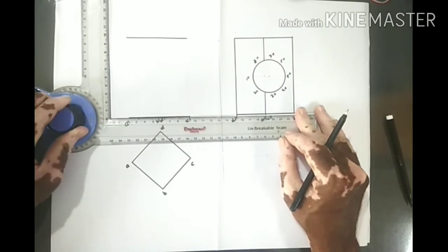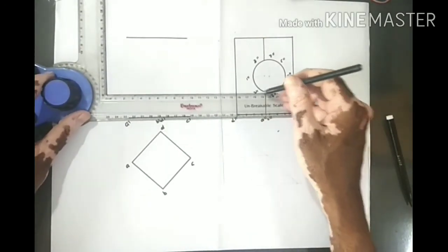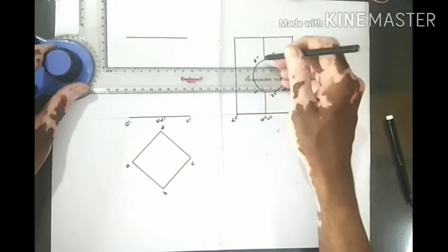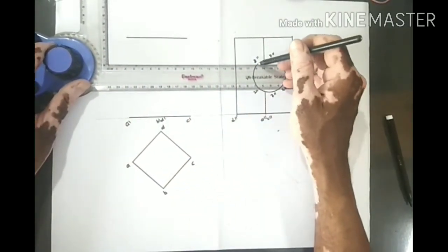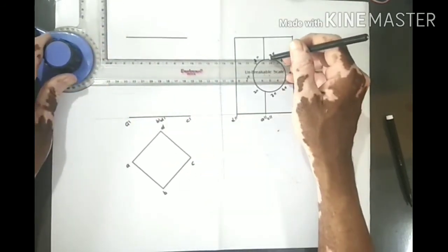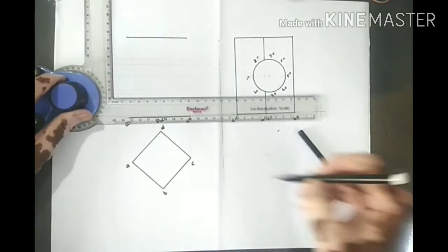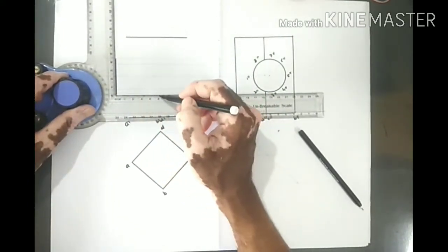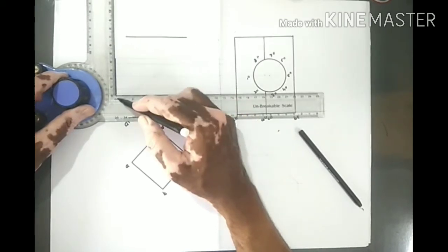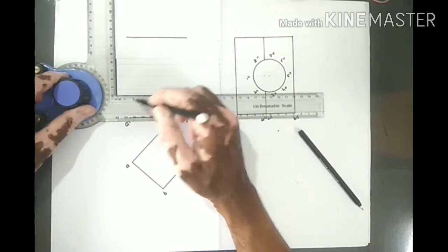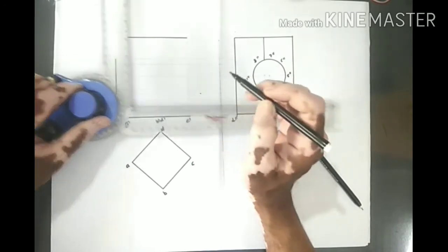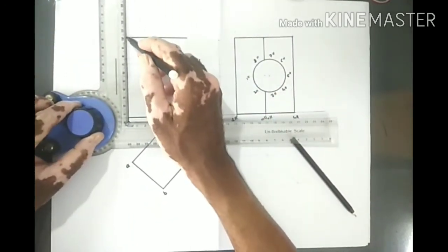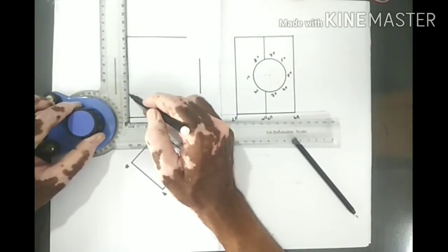So in front view it will look like rectangle. So project these generators. This generator, and the length is 100, so 50 mm from the center of the vertical prism to left hand side and 50 mm to the right hand side. So this will be like this.